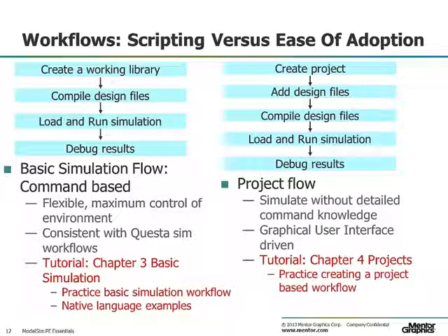It eliminates the need to remember a conceptual model of the design. The compiler order is maintained for you in the project file. It also removes the necessity to reestablish compiler switches and settings for each session. These are stored in the project metadata, as are mappings to the source files that allow users to share libraries without copying files to a local directory. There are other advantages to using a ModelSim project file, a .mpf file, that's also described in Chapter 4, called Projects.